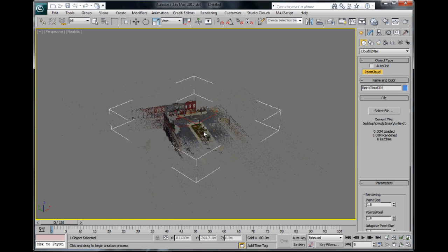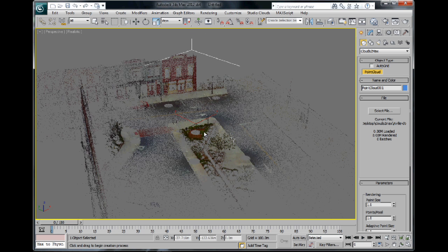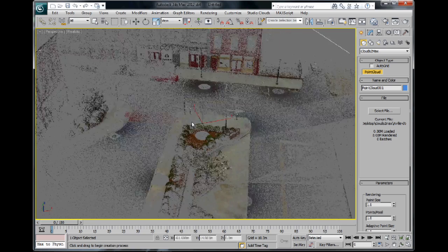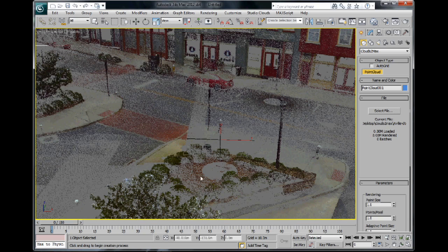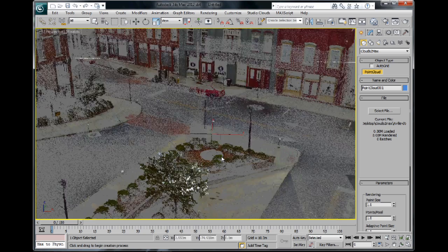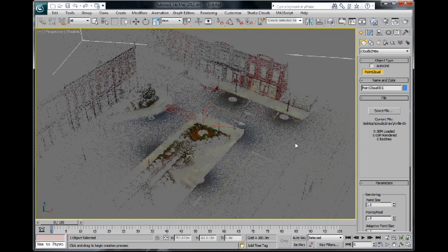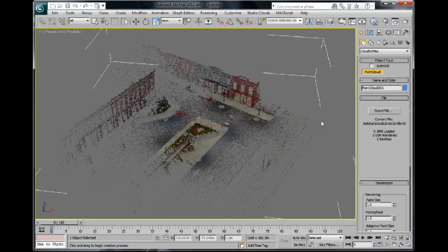The location and positioning of the point cloud when you put it in is based on the origin point. So when I hit the 0 pointer, I clicked near the origin anyway, so you can see here that I've got one of the scanner positions. It looks like it was the reference scan that was used here. So you can manipulate that and change that as well. I will show you that in a minute, but for the moment I have this scan selected.